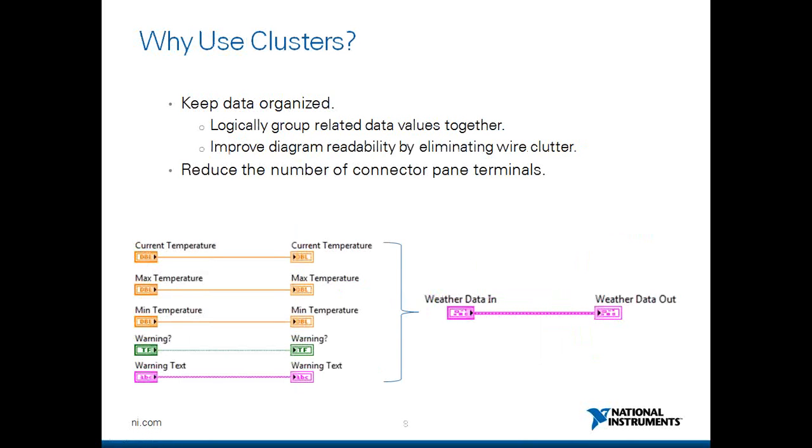Now we will go on to learn what these are. So when we use clusters, if you're going to be working with different data types, but all of them pretty much working towards the same application, then you'll go on to use clusters. And also just look at this picture on the bottom. Imagine using 5 different controls and indicators on your block diagram, which will go on to unnecessarily clutter your block diagram. Instead, you can simply wire all these controls into a cluster, which would look much neater as shown on the picture on the right.